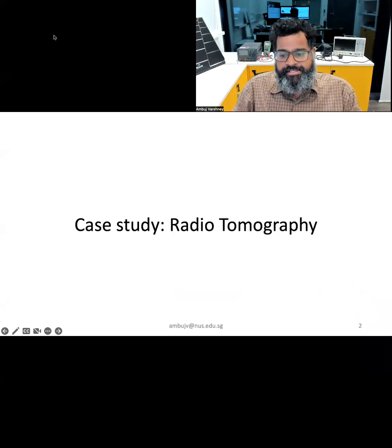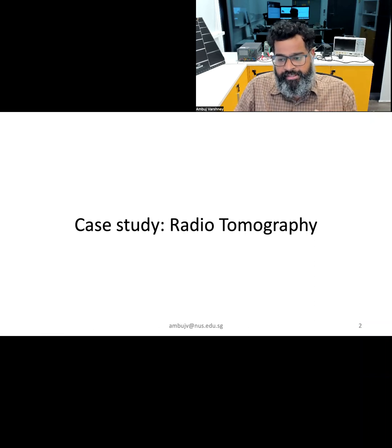So in the previous lecture, we had looked at using received signal strength to estimate the distance of a target from the anchor node. Now let's look at a sensing system called radio tomographic imaging that uses a drop or attenuation in the signal strength of the radio signal to enable applications ranging from human vital detection to localization.